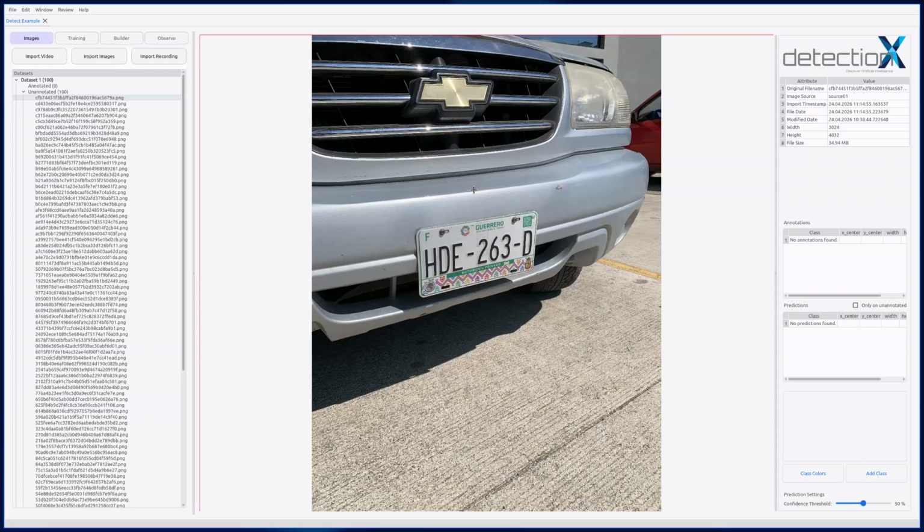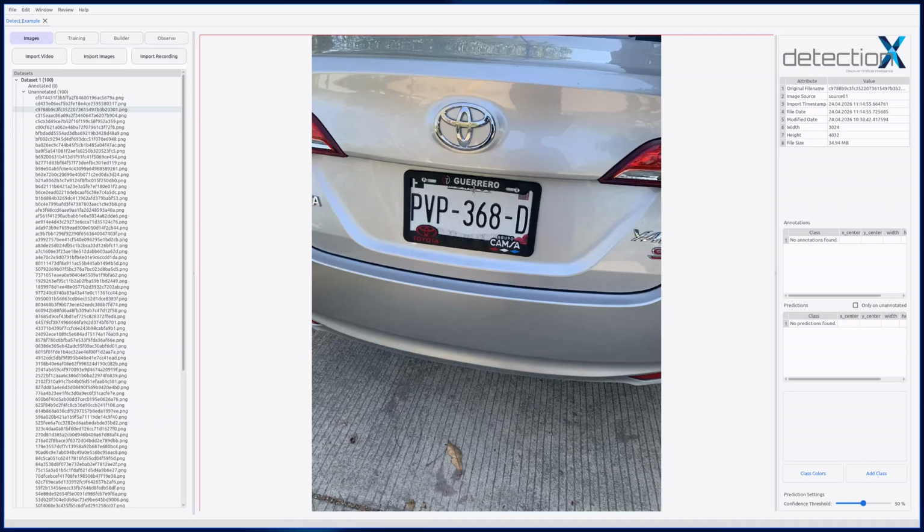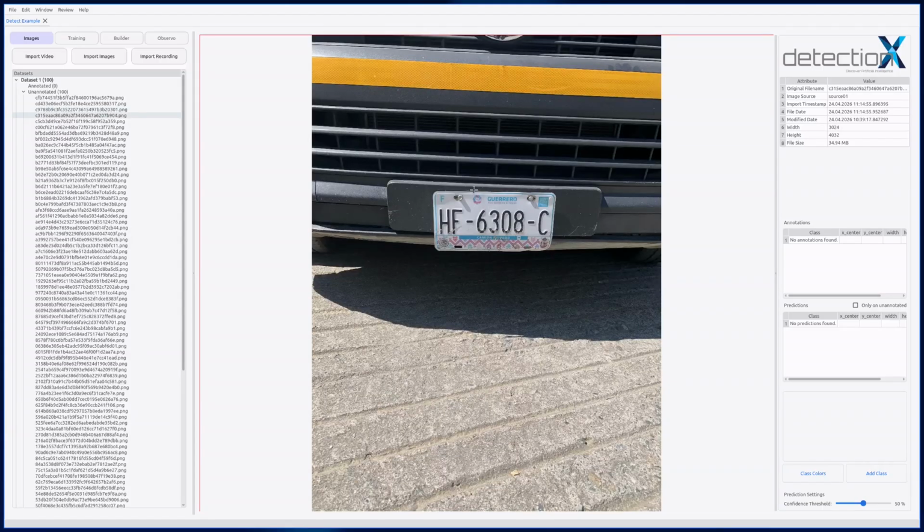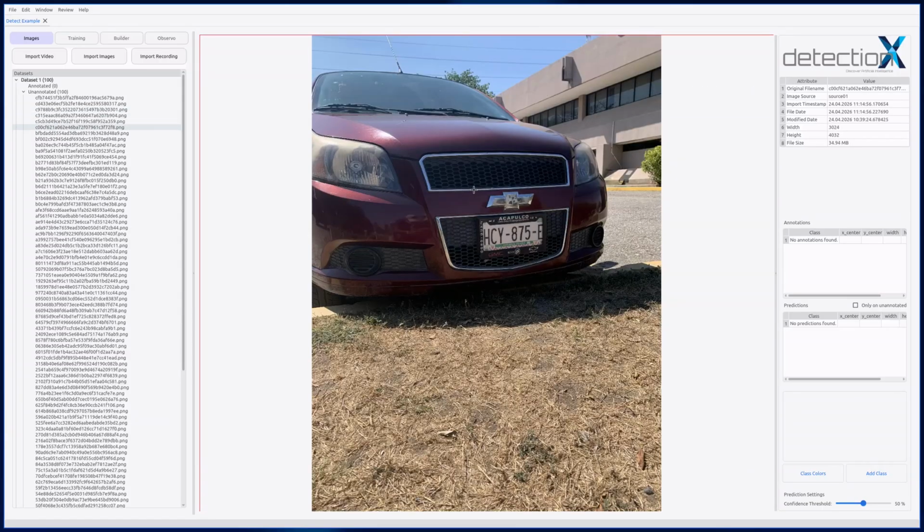After completion, all images appear in the image tree on the left side. We can navigate through them using the arrow keys. To begin annotating, we simply click, hold, and drag with the left mouse button to draw a bounding box on the image. If no classes exist yet, Profundus will ask for a class name after releasing the mouse button. We enter a name, confirm it, and this creates our first class and first annotation.